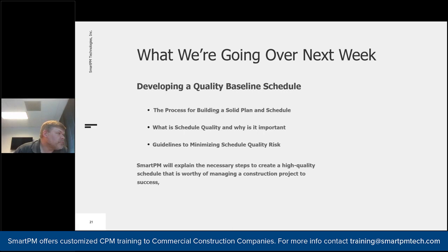Can you please elaborate on the resulted period for which the contractor is entitled for a compensable extension of time and the best practices to assess monetary value accordingly? Okay. That'll be something that we cover in a few weeks from now when we talk about delay analysis. But real quick, when a contractor has something that happens that impacts the critical path of the job to a point where the end date is pushed out, and it's provable that it occurred and it was a critical path delay that they did not cause, then ultimately they are usually allowed an extension of time. Now, if it's something that they did cause, they are not.